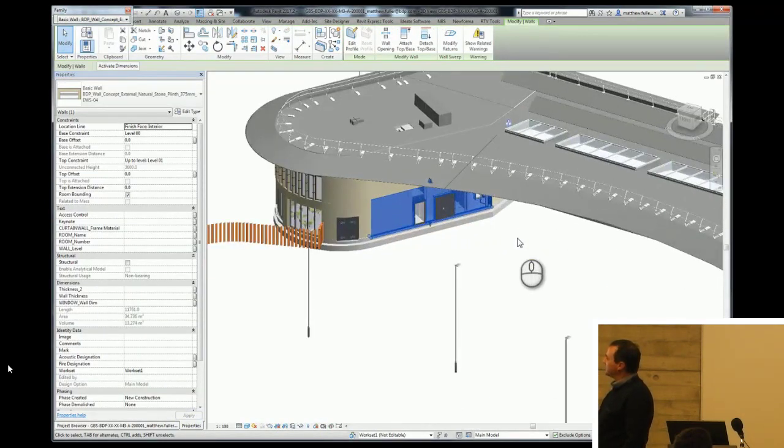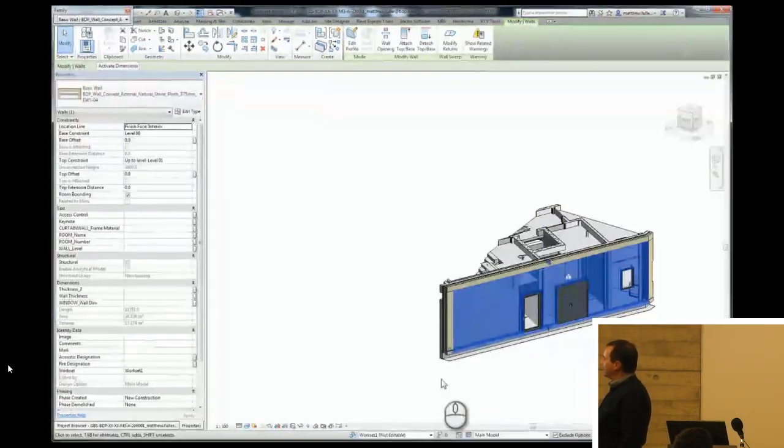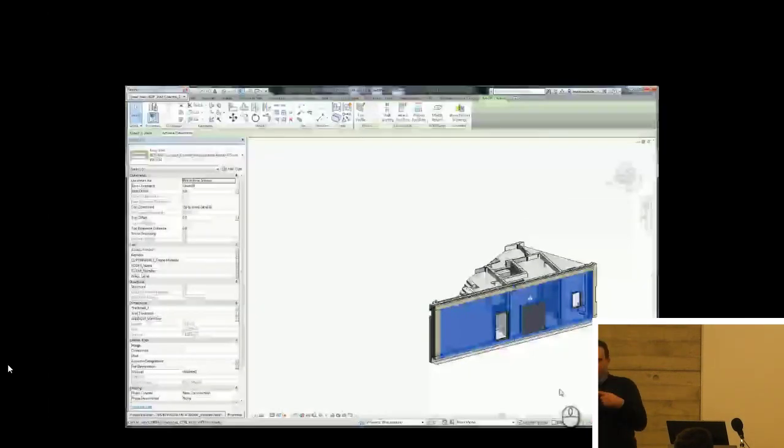So those elements are still selected, so you click on that section box, and you've isolated the elements. So you can imagine when you're doing clash detection and you find two elements, you use this tool, very quickly take it back into Revit so you can manage the clash.